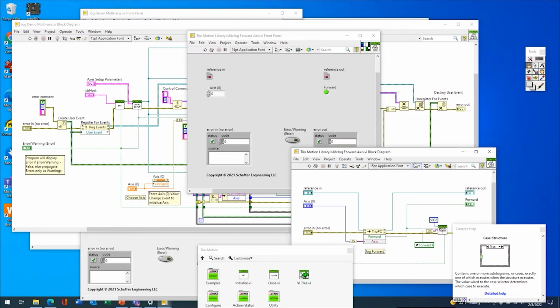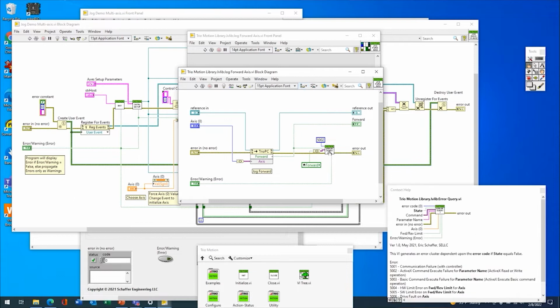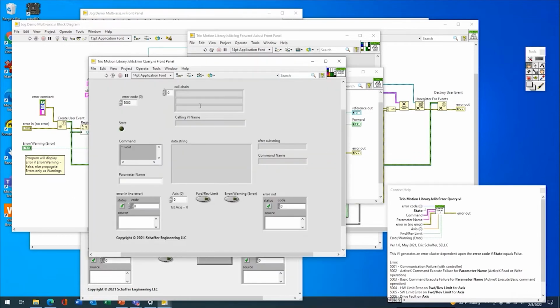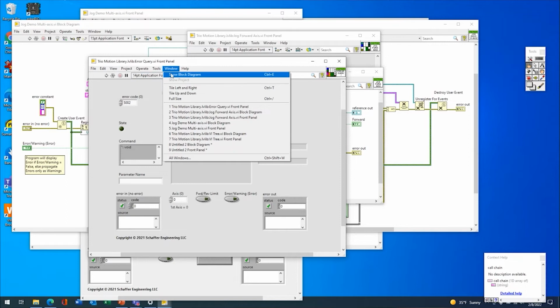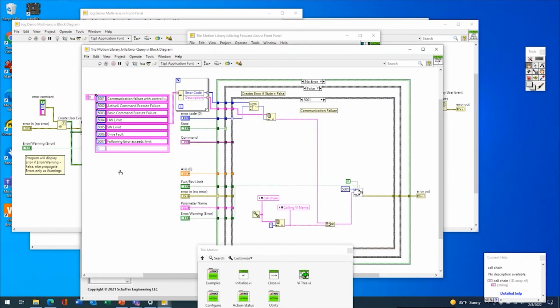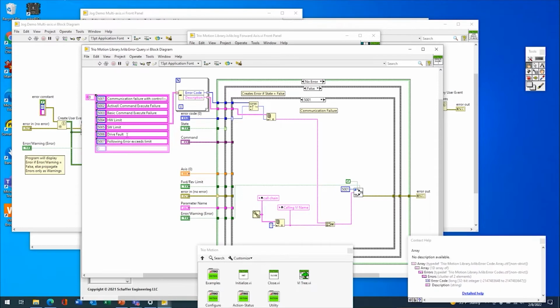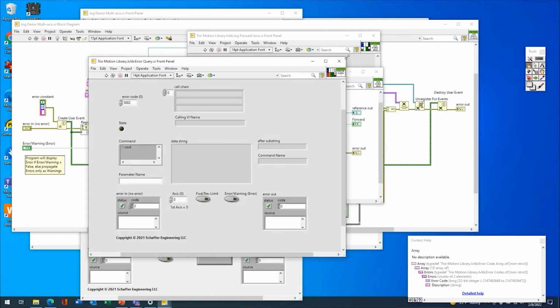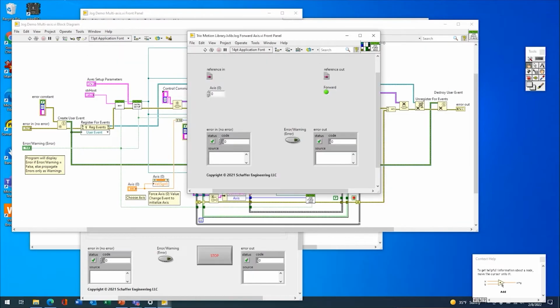This VI will handle every fault that can occur and give you communication or data on your error, what it looks like and what is on that axis. Everything from communication to command errors to limits, software and hardware limits, drive faults, and following errors on the servo. So you've actually got a little troubleshooting guide built right into your interface, it looks like. Everything is built in. Great.